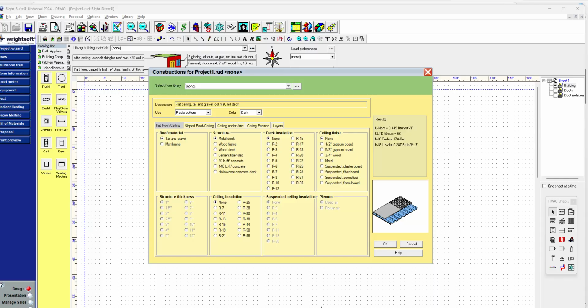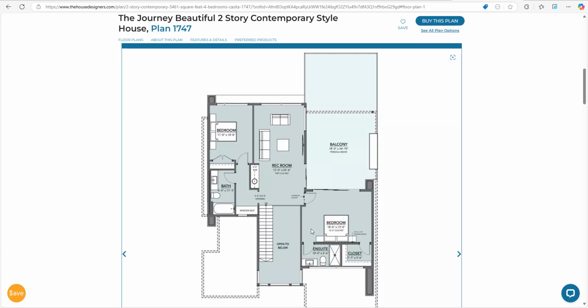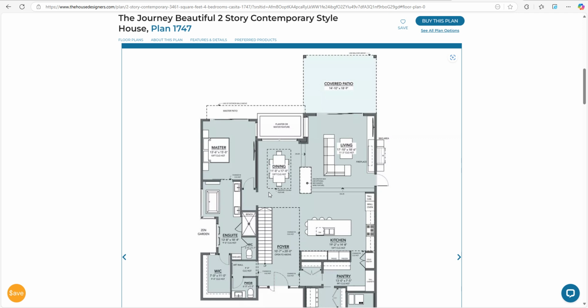The reason being that when you're on the first floor, the ceiling of the first floor is actually the floor of the second floor, right? And it's all one shared air space, because the air flows from the second floor to the first floor. It's all one conditioned space. So you could look at that from a heat transfer perspective as though it's perfectly insulated.